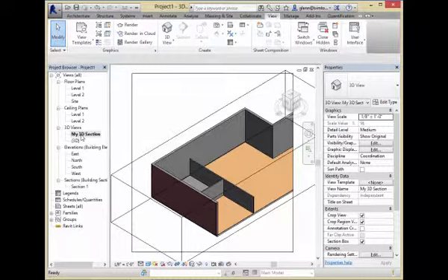And how about getting rid of the box? If I get rid of the box in that view, does it get rid of it in all the 3D views? Each view has its own section box. Okay. And although it looks like it's showing up here, when you print it, it won't show up. It's just hanging around there as a visual indicator. You can hide that section box. It's still active even though you can't see it. But if you hide it and you can't see it, then it gets a little confusing.